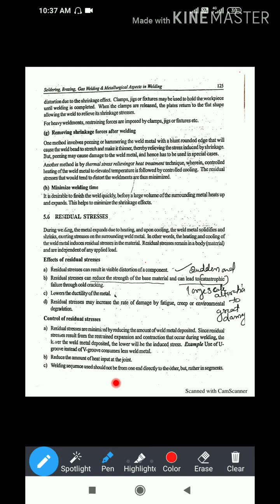In the same way in welding, the electrode should move frequently so that an equal amount of temperature is distributed to both workpiece edges which are going to be joined, and an equal amount of weld is deposited. By this, the residual stresses can be controlled and reduced.